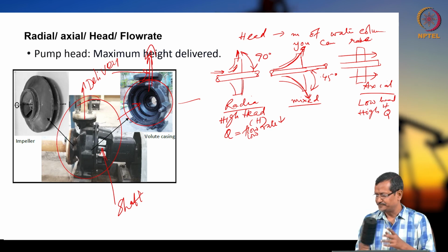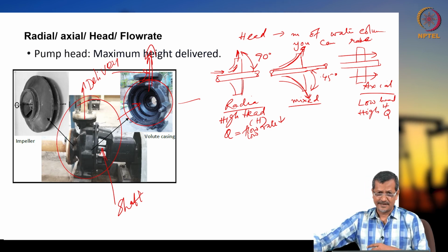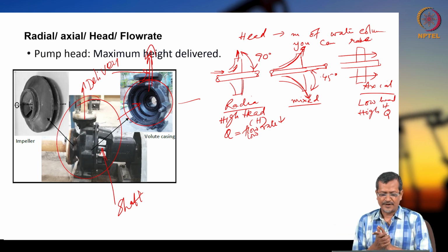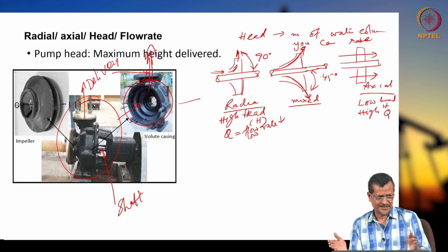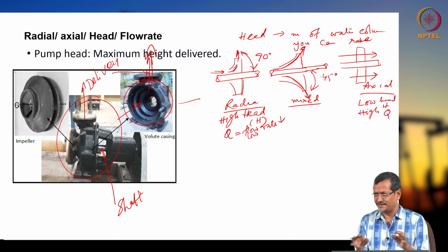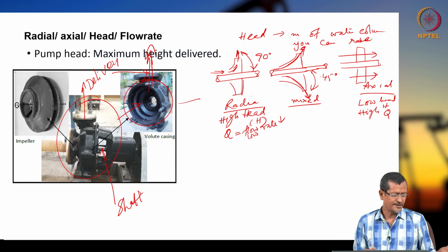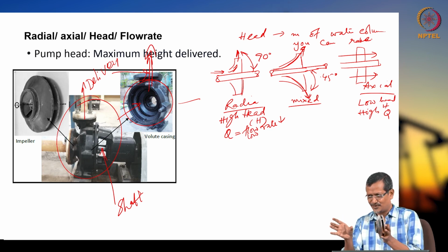Simple solution, right? Okay. Now, surface production operation, why am I talking about ESP? In surface production operation also, in many cases you need a higher flow rate and you need higher head also. In that case you can create multiple stages of centrifugal pump. I will not say ESP then, because it is not submerged, it will be on the surface. So I can create rotor, casing, another rotor, casing.